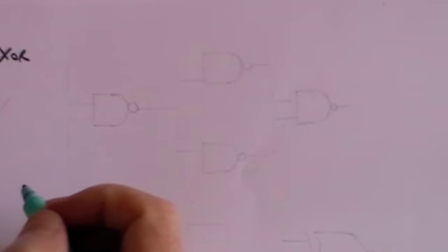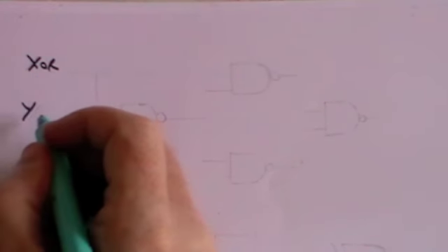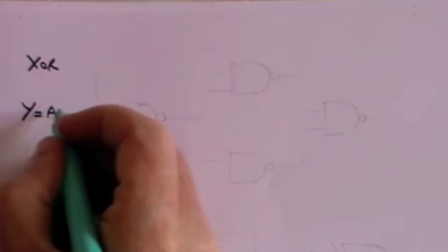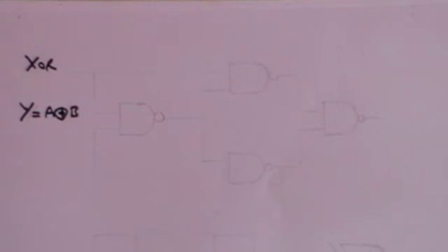The next one we're going to do is the XOR gate, and let's move that over so you can see it, and that has the representation Y equals A plus in a little circle B, where Y is the output, don't forget. And that means that either one of the inputs is positive but the other isn't. So one can be positive but not both. And here we actually have to use other gates. They will contain transistors, but we need to use 4 NAND gates to create an XOR gate. And that's how you start to see how these gates build up in logic terms.